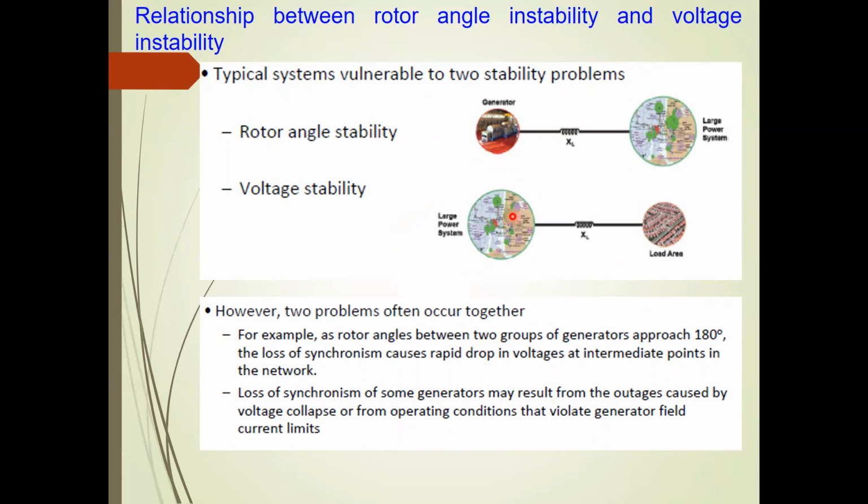Remember one thing. In most of the cases, when we refer to the report of the blackout occurrence, we observe that before the blackout occurrence, the frequency in the system is very much stable. The voltage in the system is very much stable, within the nominal value. But the system is stressed. The system is highly stressed, because let's say you don't have much generation and you have high demand, though you are able to control your system and regulate your generators to meet the demand. Let's say you have several generators in a network and you have the load, and all the generators are feeding power to the load, no problem, this is an okay condition.